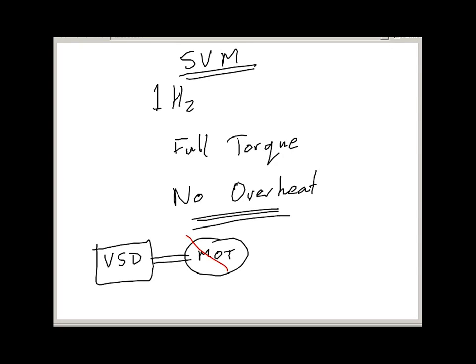If you ever have to replace the motor with another motor, then what you have to do is wire it all up, and then put the VSD into a learning mode. I think in a lot of cases it's only a case of pressing a couple of buttons and waiting half an hour. And then what the VSD does is it winds the motor up and down for half an hour or so. It's called a magnetization, is it, on your one? Well, basically the VSD goes off and learns how the motor works, and it learns that motor's magnetic fingerprint.